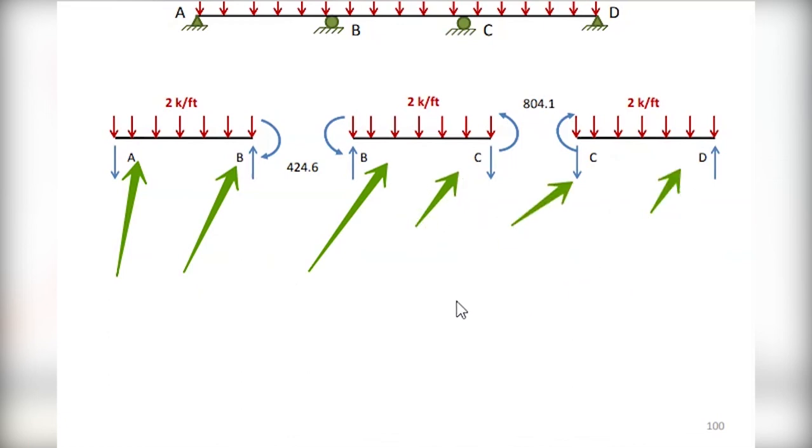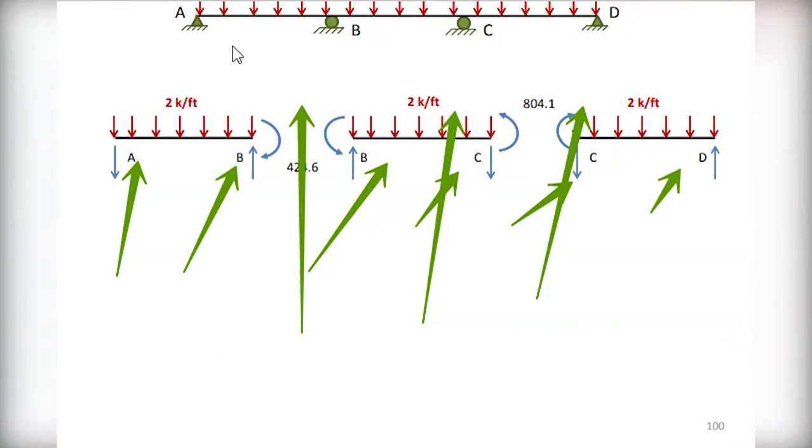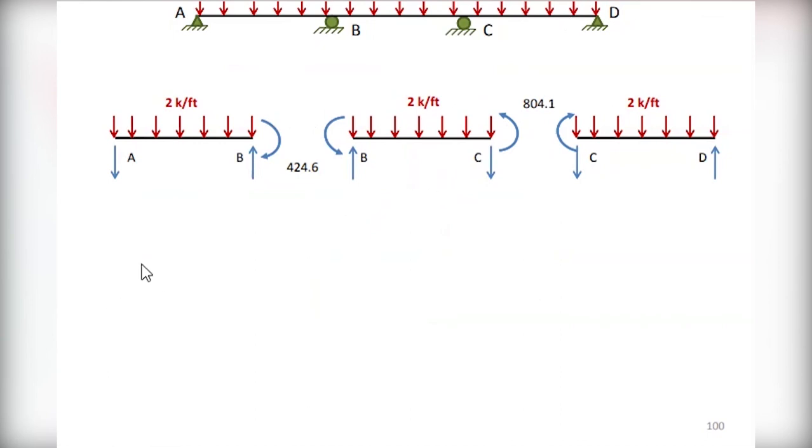After having the reactions, we'll be able to calculate the shear force at your member. On calculating the shear force for the member, it will be easy to draw the so-called shear free body diagram and the bending moment diagram. On calculating it, the shear and the moment diagram can be obtained, and you can have the value for the maximum shear at the support and the value of the maximum bending moment at the middle span. So by this value, you can now go to design the reinforcement to withstand the bending moment and the shear at the support for the stirrup.